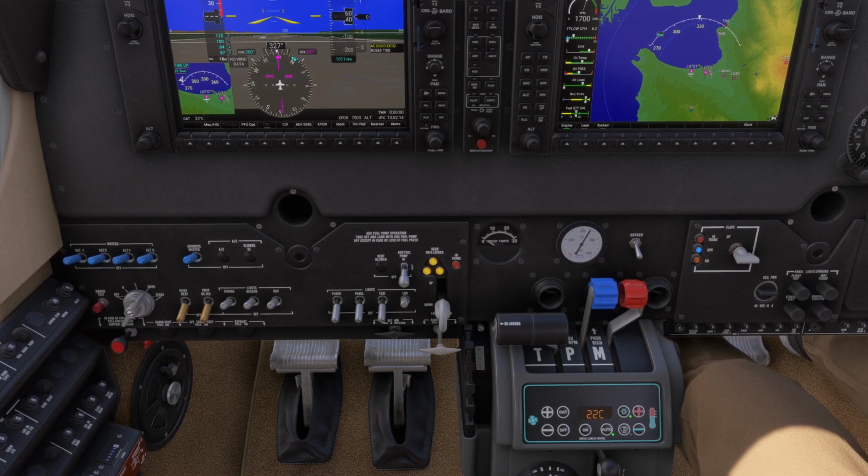Even if the engine is shut down, while the engine oil temperature is above 40 degrees Celsius, the system can provide enough warm air to have some heat in the cabin or on the windshield.